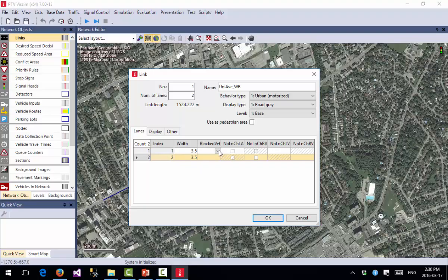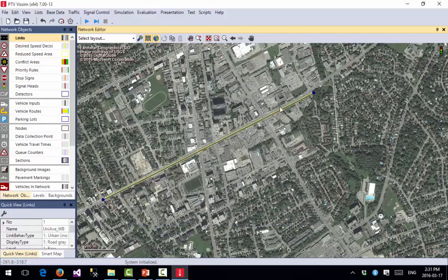I can also block some of the vehicles from that network. For example, I want to simulate a network that has a dedicated bus route, so I will eliminate all of the cars except the buses here. Or I can block all of the network vehicles, or I can say that there are no lane changes. So I will click OK.